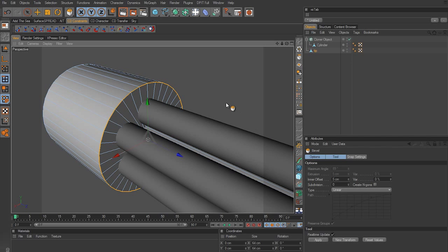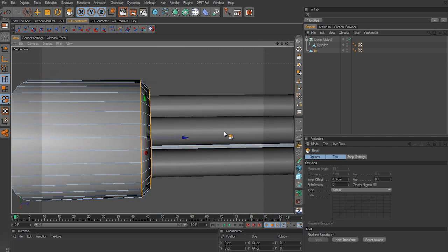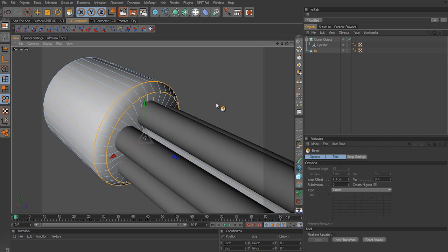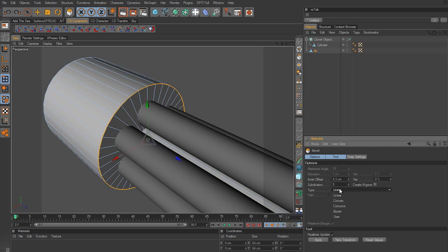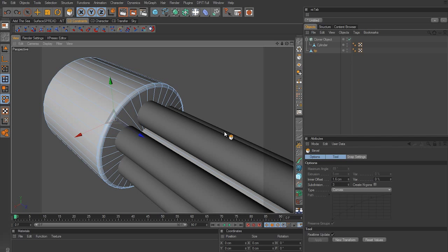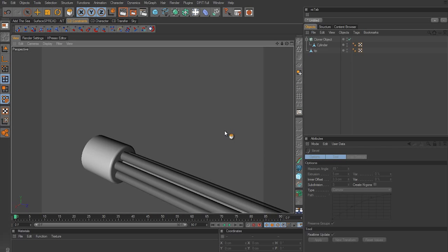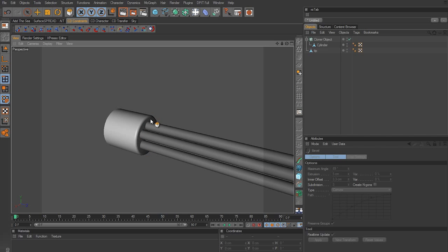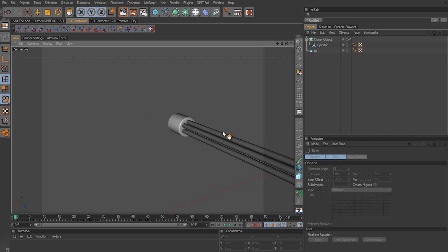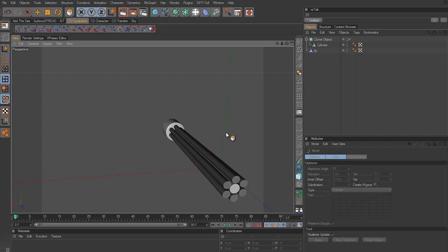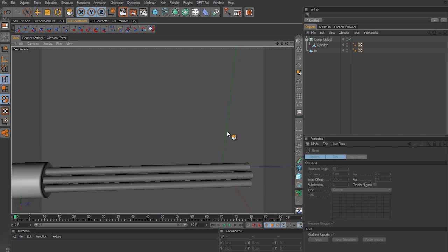It's currently set to linear, and if we choose linear and bevel, that's what it's going to look like, and I kind of want a rounded bevel. So we need to choose convex, and I want a subdivision of about 3. So now we'll bevel again, and now we have a nice rounded corner on that backside, and that could possibly pick up some highlights when the camera is kind of moving around behind the gun.